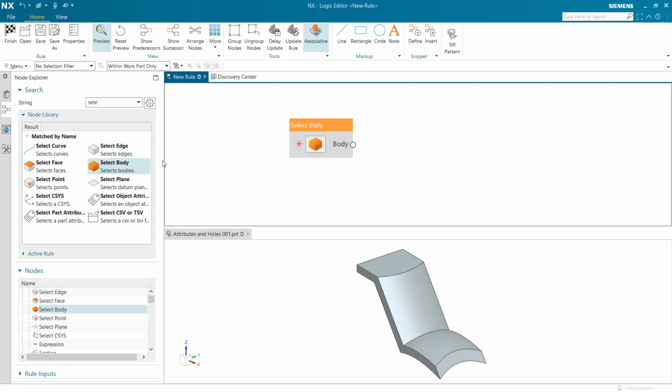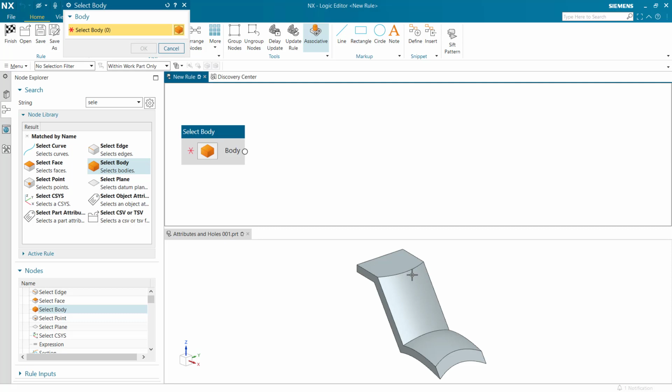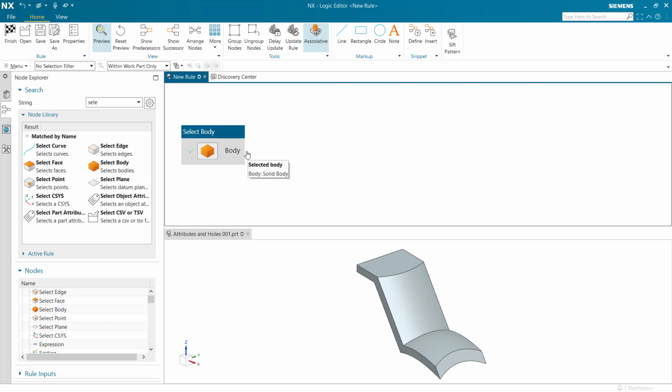In this example, we shall use these capabilities to identify the faces on the structure that have a defined attribute called hole grid, and create counterbore holes normal to those faces at their specific center locations. To identify all the faces of this body, we shall deconstruct it first.